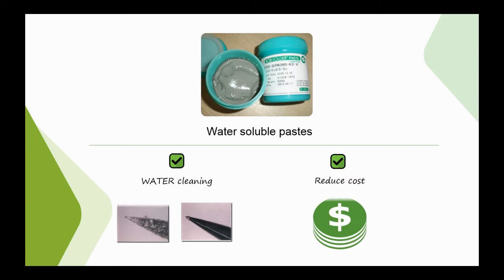Water-soluble pastes. Due to technical reasons in early manufacture, too much residue remained on the PCB surface, badly influencing product quality, and electronic properties weren't ideal either. Manufacturing mostly used a cleaning process with CFC, but it wasn't friendly to the environment, and many countries have already prohibited it. Now the water-soluble paste is common and it can be cleaned when soldering work is done, which reduces product cost and meets the environmental requirements.